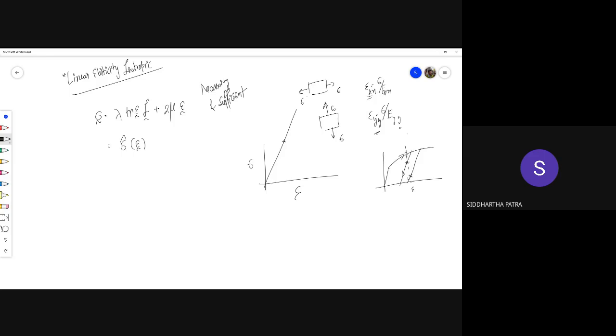Okay. But if it is said that the constitutive relation is just a single line, and it doesn't matter whether you are loading or unloading or doing anything. Okay. So even with a nonlinear relationship, if it's just a single line, it has to be elastic, like hyperelasticity. Now, if it is a straight line, and that is the only relationship between stress and strain, and any moment you know the strain value, you know the stress value, and you do not need to know what has already happened to the material, whether it has been previously loaded and unloaded, now it is being unloaded, or now maybe it is being reloaded.